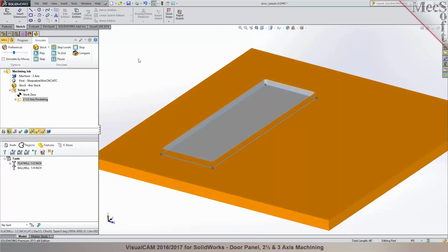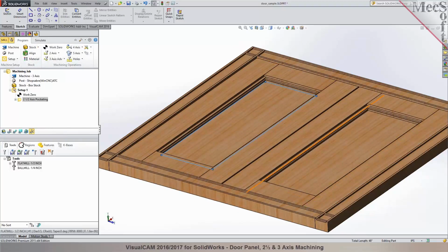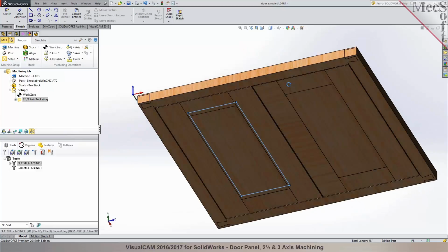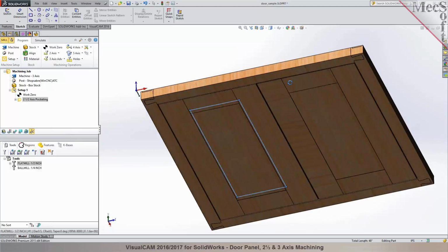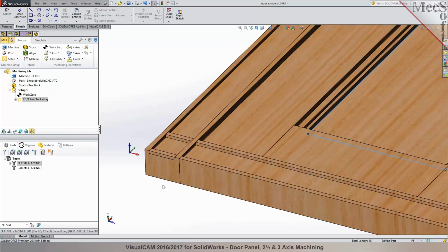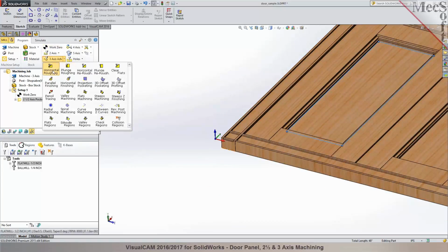Now this is one of the ways to program the toolpath. Now if you'd like to automatically program all of the features in one pass or one operation, you could program it using a 3-axis toolpath in here. You can basically just pick a boundary and program it using a 3-axis toolpath. So one of the ways to do that would be, in this case, if I don't want to cut past the extents of the stock, I can create a boundary in here. So I can go to 3-axis and choose horizontal roughing.